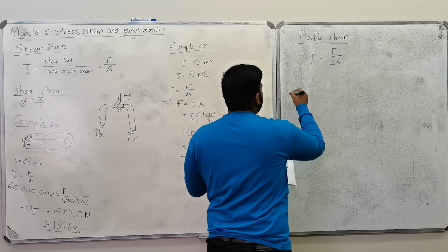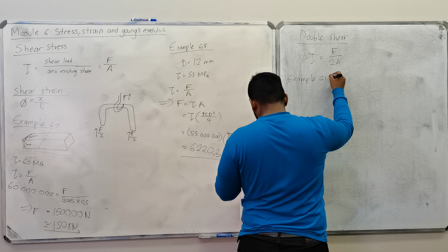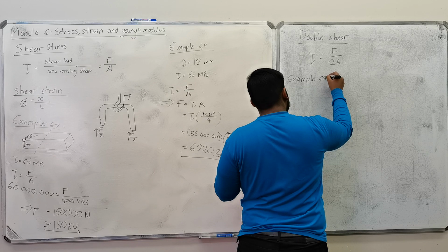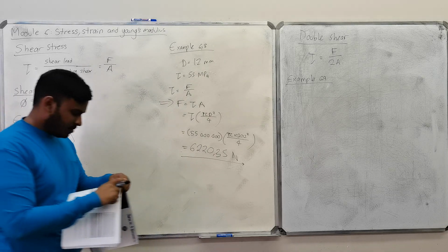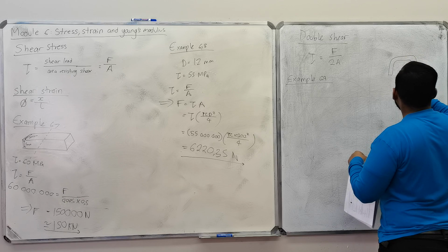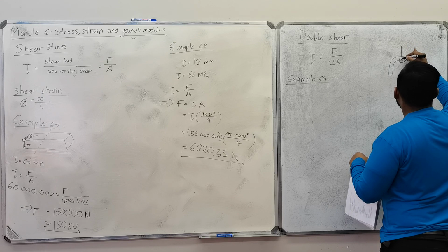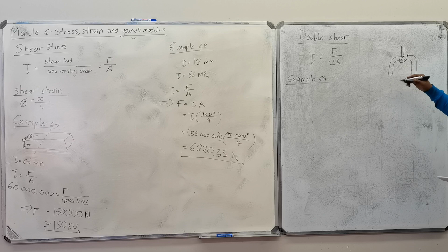If you look at the example, this is your clevis, right? That U shape. Whatever you want to hook it onto, say that piece has a connection like this, it will fit into the U shape, and then you would normally bolt it there. So we're basically working out what stress or strain would affect this bolt.